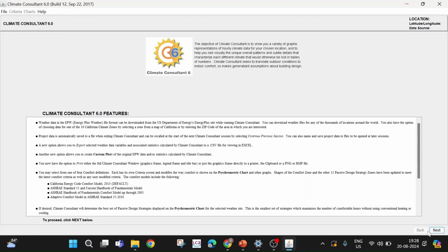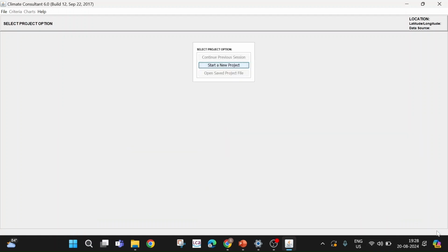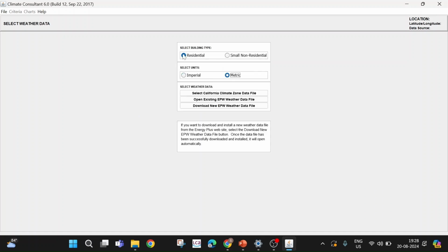Yes, sir. So these all you might have done. You will be starting a new project, metric, residential, that you can do. So I was talking about this one. Open the second one, existing EPW. What is EPW? Energy Plus Weather. Absolutely right. That is Energy Plus Weather data files. So I'm clicking into that.